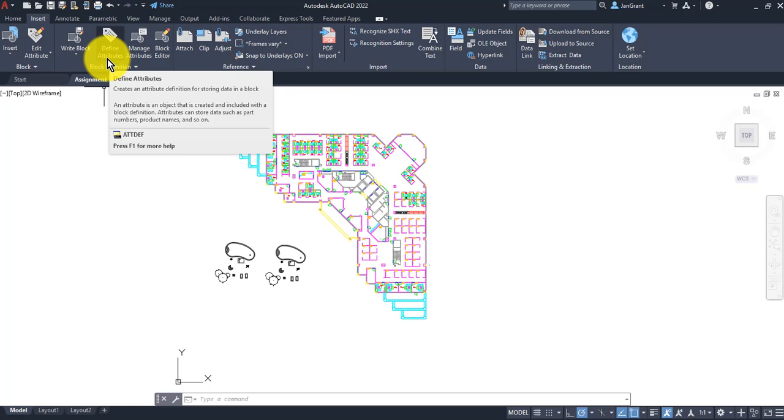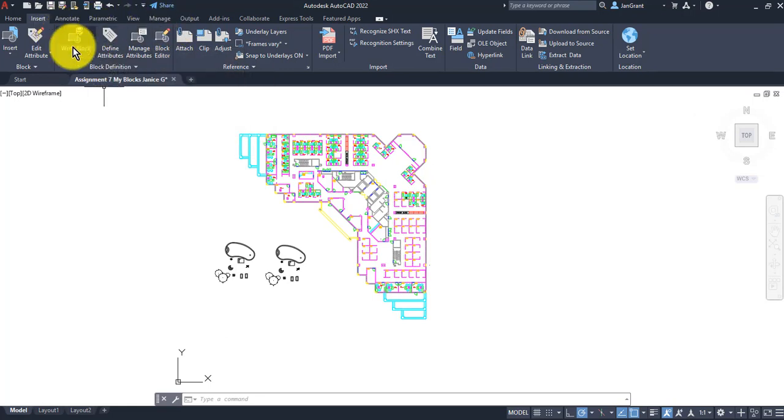You'll see this a lot of times in title blocks, like the information of the sheet number and who drew it. What it basically is, is a database of text that's within the block. Instead of trying to edit each one of the text strings, you are creating your own dialog box based on those blocks. Okay, and in the sample file folder, there are some files that have those attribute blocks. You can go open up and check it out.